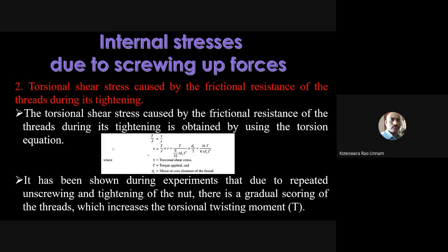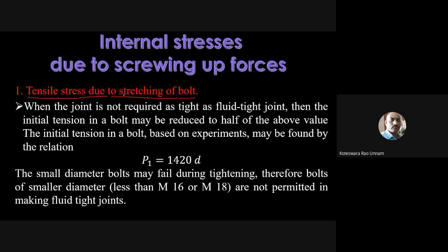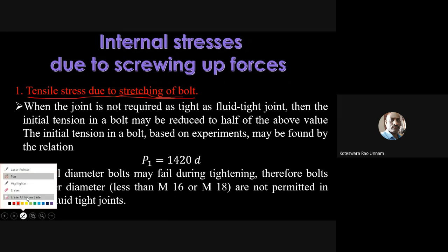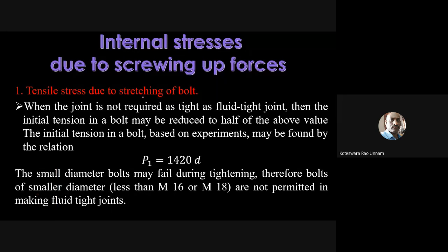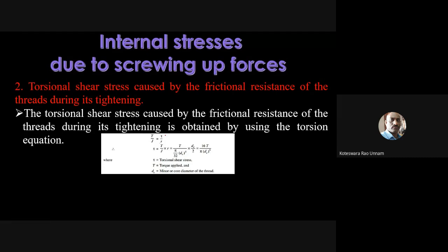Now, if you compare the magnitude of these stresses with respect to your tensile stress, their magnitude may be small, or sometimes we may not accurately compute their magnitude. So in those situations, what we will do is design only based on this tensile stress, and apply some factor of safety to account for the remaining 4 types of stresses. Okay, this is what we need to remember.